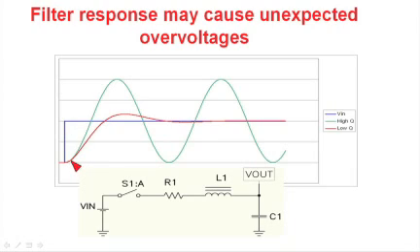If we have a very high Q system, or that is one where the resistor is quite small, we can see that we can get very severe overvoltage conditions in our systems. We can have overshoots as much as 100% with this voltage step. So that might mean if you had a 48 volt system, you could have a 100 volt peak applied to the system, and that might cause damage in your system that you didn't anticipate.